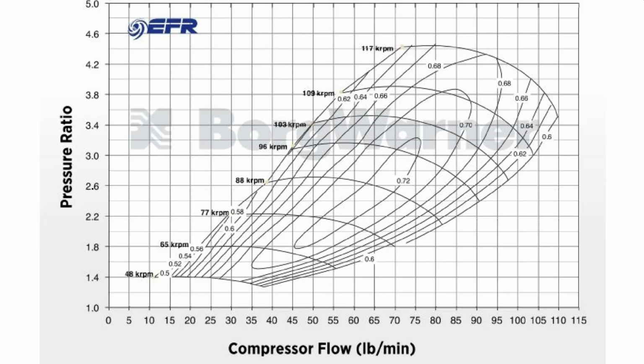Looking at the compressor map one more time, if the MAP sensor system failure was instead causing the ECM to measure MAP as higher than what it actually is, the ECM would over-predict the mass airflow. So it would indicate that we have much higher density of air in the intake manifold. This would cause the compressor ratio to be under-predicted. So we would show a compressor pressure ratio that was lower than actual, and that would result in the estimated MAP being much lower than the actual MAP.